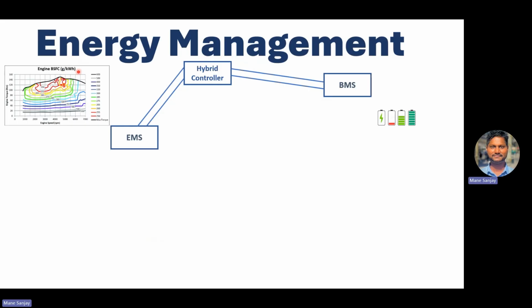given basically as a fuel consumption rate: how much fuel is consumed per how much power is produced, in watts or kilowatts. Any engine, which this EMS controls, will have different BSFC values at different speeds and loads. For example, a reciprocating engine achieves maximum efficiency when its intake air is unthrottled and the engine is running near its peak torque.